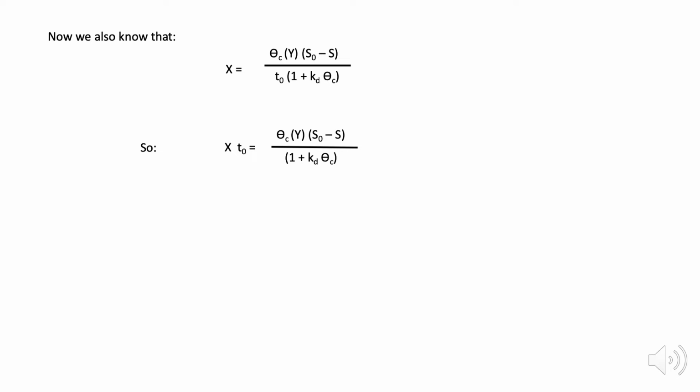They're independent variables. So the hydraulic retention time is the average amount of time water spends in the system, and the mean cell residence time is the average amount of time that cells spend in the system. And depending on how we operate the clarifier, we can keep the cells in there as long as we want them, independent of how long the water stays in the system.